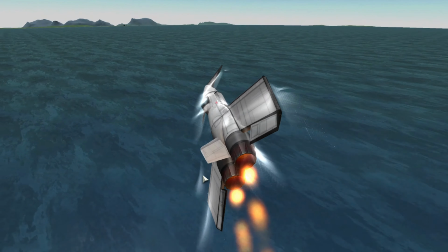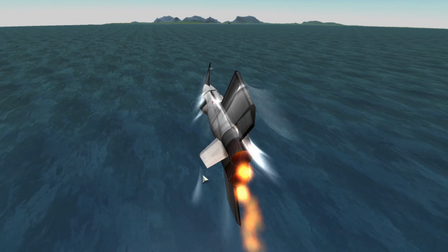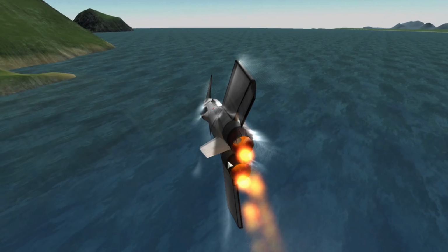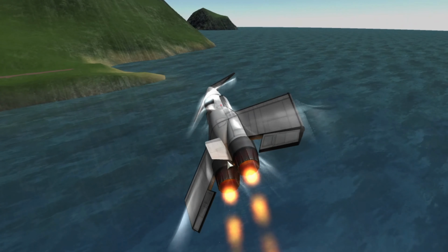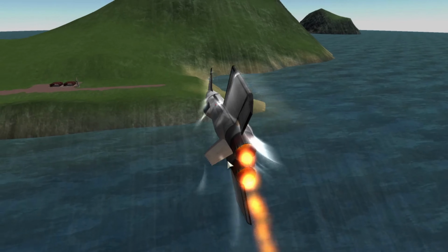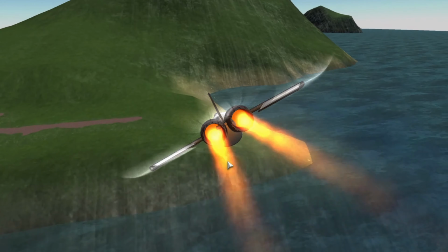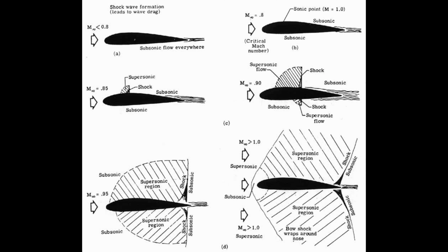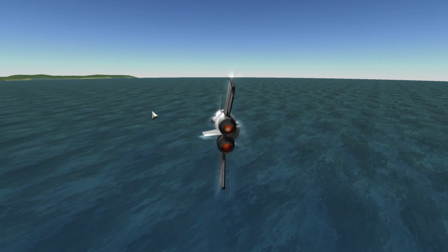The spanwise flow will increase the boundary layer at the tip of the wing. A boundary layer is an area just above the surface of a solid, where the fluid moving over the solid moves slower. An increase in boundary layer makes the wing create less lift because there is a larger barrier between the airflow and the airfoil. This means that airplanes with swept wings will stall at their wingtips before they stall at their bases, and the tip of the wing is where the ailerons are. And ailerons are used to control roll, so airplanes with swept wings will lose roll control at low speeds.